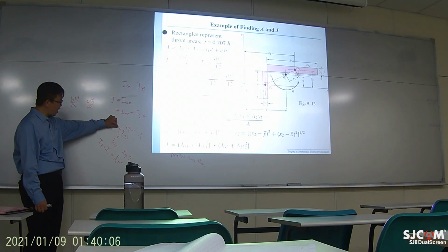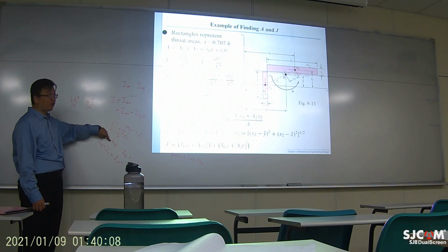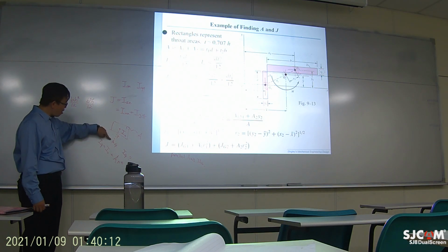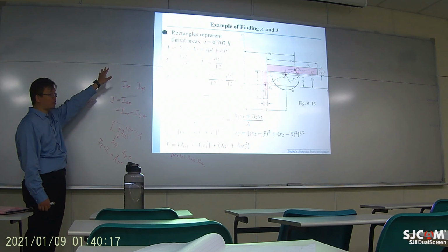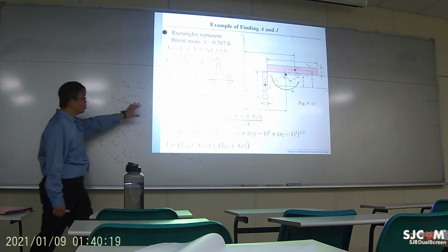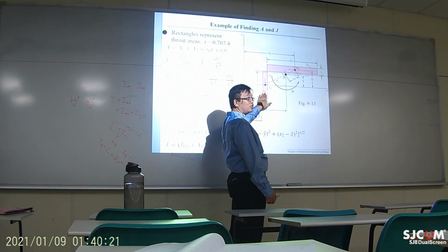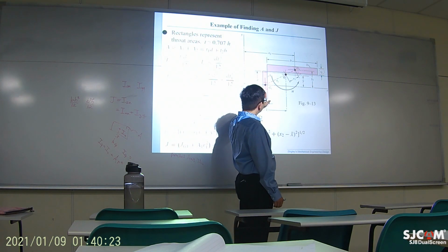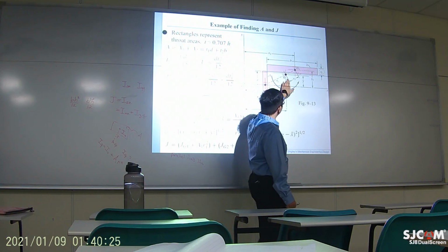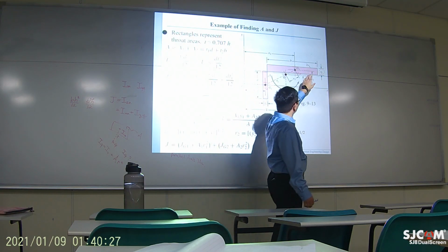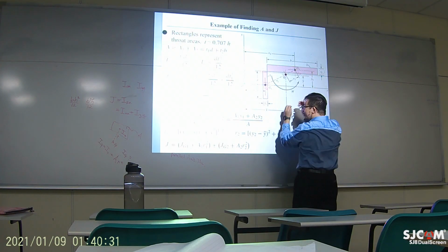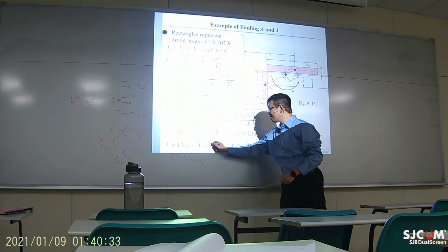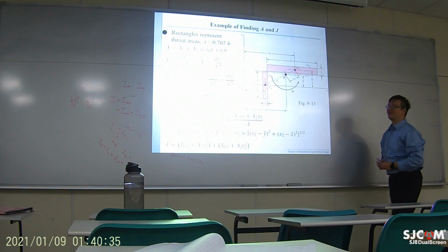Okay, that's how you can compute the polar moment of inertia about some center outside of its own geometrical center. So you need to do that for this JG1. You need to shift its rotational center to here, and you need to do the same thing for this part as well. So you shift both to G and then sum them up. So that's why you have a plus right there.